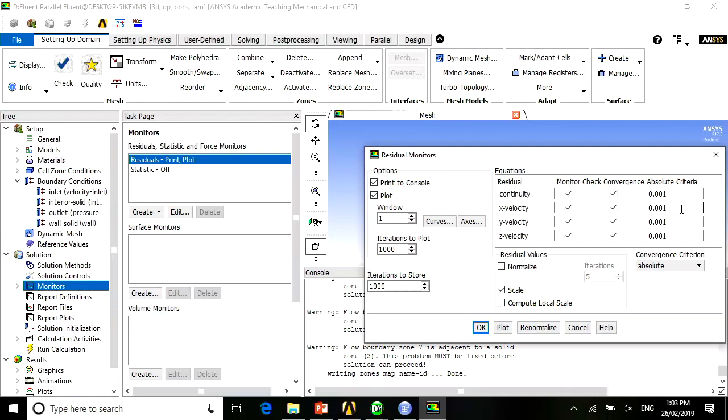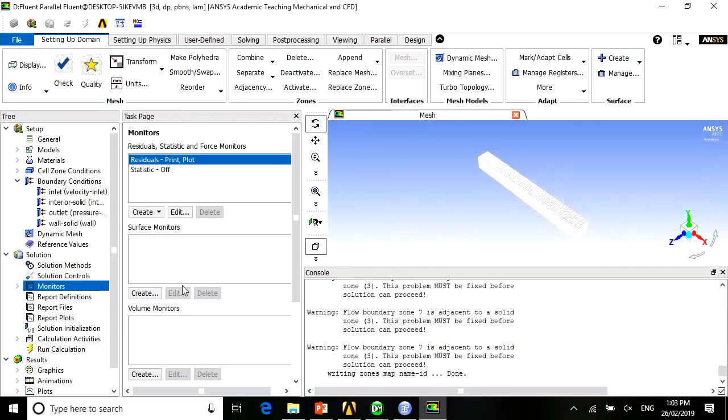It's running again. So what Fluent does is that it normalizes its residual according to its own method, okay? So just accept that they have done a good job and the residual is what it is. But still, if you are using Fluent for your group project, make sure you try other criteria, like instead of 1e-3, it will be 1e-4 or 1e-5 and so forth, okay? Now,